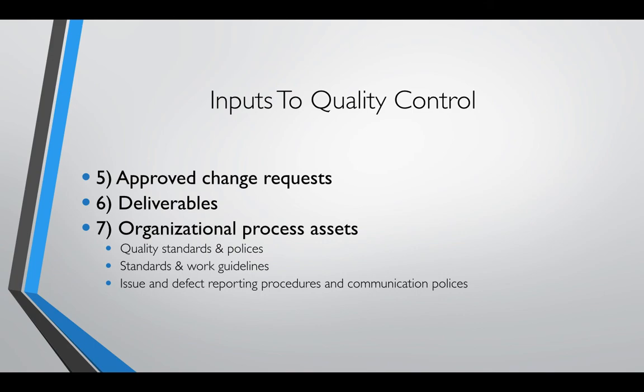Where would you find out that you need this type of inspection, or that you have this type of work that requires specific inspection agencies? Of course, you go back to the RFP, to your contract documents. They will state what type of tests are required on this project, and your quality control plan is going to lay out the certifications and qualifications needed for this inspector to be on that project.